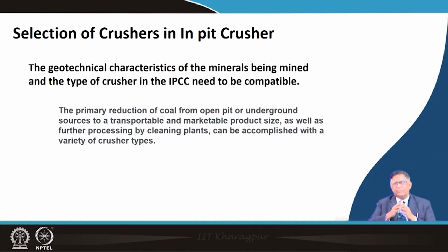For that, a case study is the Neyveli Lignite Corporation. At one stage, I think between 1980 and 1983, they purchased an in-pit crusher for their overburden. The overburden blasting always used to give big lumps, and they thought they would put it through a crusher.